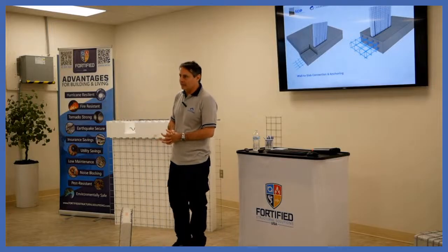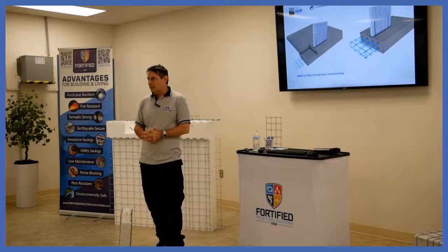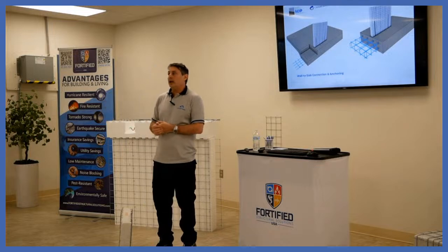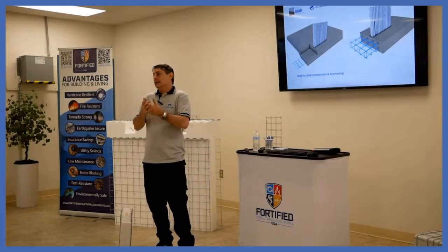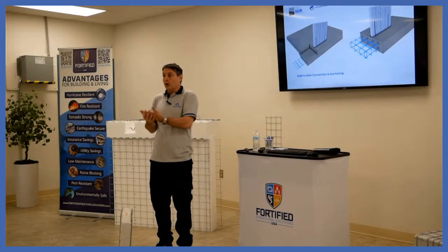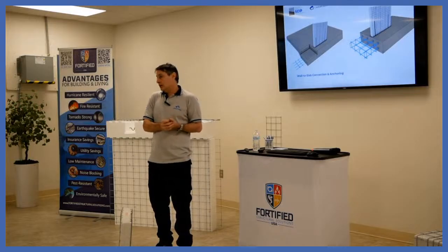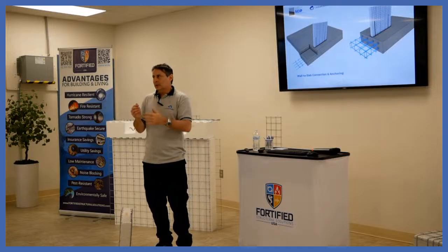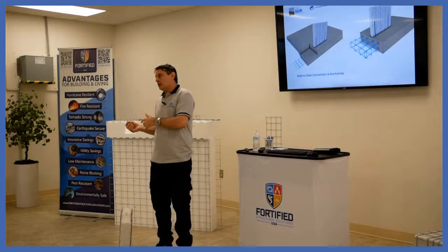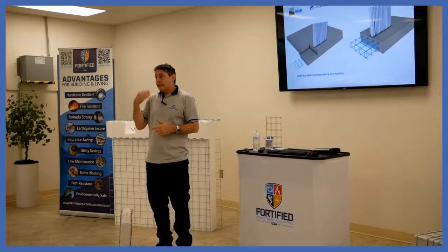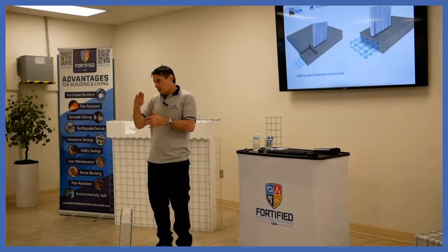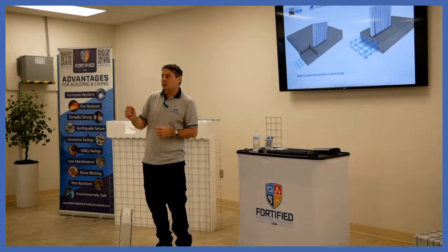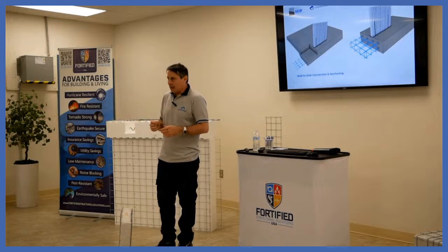Now he is asking about the maximum loading capacity. You're speaking about the floor panel. Yeah, there are tables. I told you that there are tables from the different manufacturers that tell you about the capacity for walls and for floors. For floors, you have three things: the shear capacity, the moment capacity, and the deflection. According to that, you have a table, and you can use, for instance, let's say a panel of